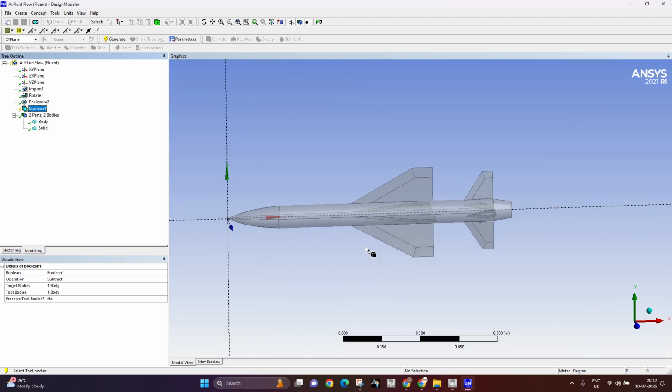Now, just have a look. It is visible. If I click on generate, the boolean will be operated. You can see the shock symbol over here. If it is shock symbol, you are yet to click on generate. If it is green tick mark, the operation is done. Now operation is not yet done. Just see, I'll click on generate, observe the design.